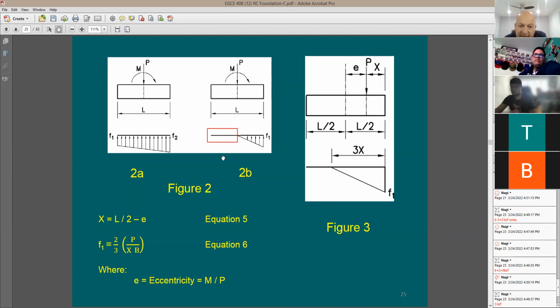Can you apply any tension to sandy soil? I'm guessing no. The sand doesn't have any resistance to that. But the sand is going to be good if you put pressure on it. It's going to be able to take this pressure of compression. But you cannot really apply any tension to it. So actually, the footing here is going to be lifting up from the soil. This is why you see here, this section of the footing has no stresses below it. And on one side, you're going to have lots of compression. And you end up with the stress distribution like this.